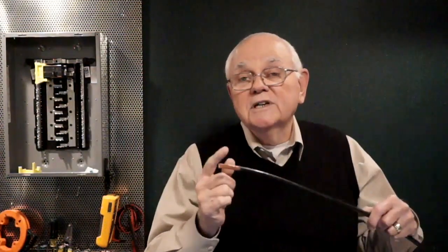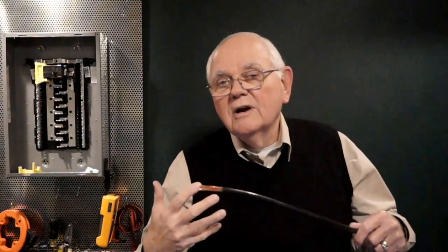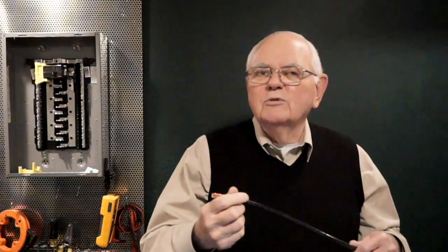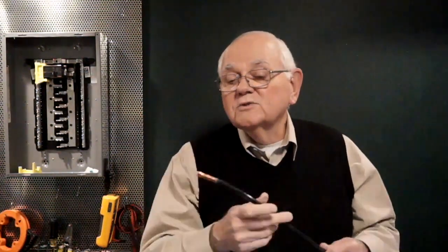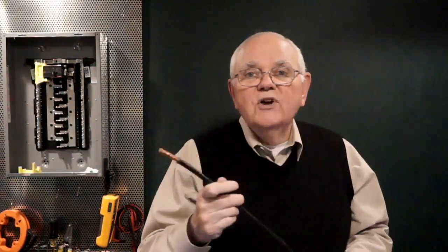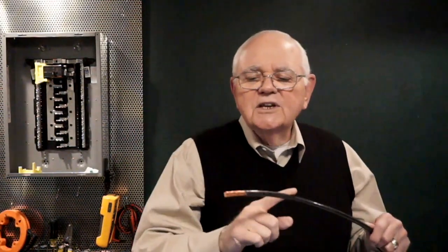So if I need to carry X amps of current through a particular conductor and I choose aluminum versus copper, I'm probably going to have to go up one size larger in my table, maybe from a number 4 to a number 2. That will vary, but you can find all of those properties in Chapter 9, Table 8. The insulation itself, depending on the type, has a lot of different properties.